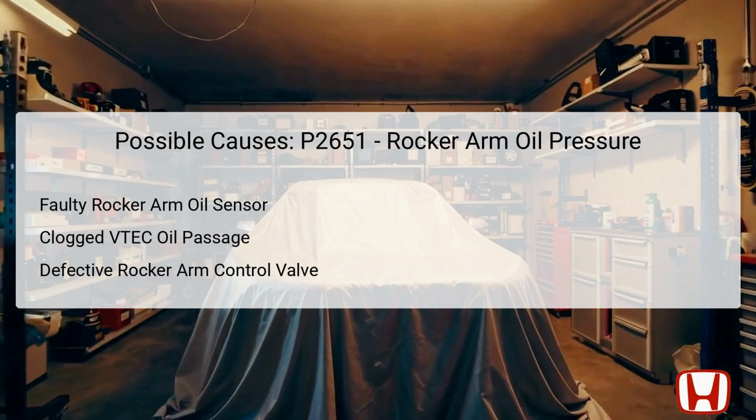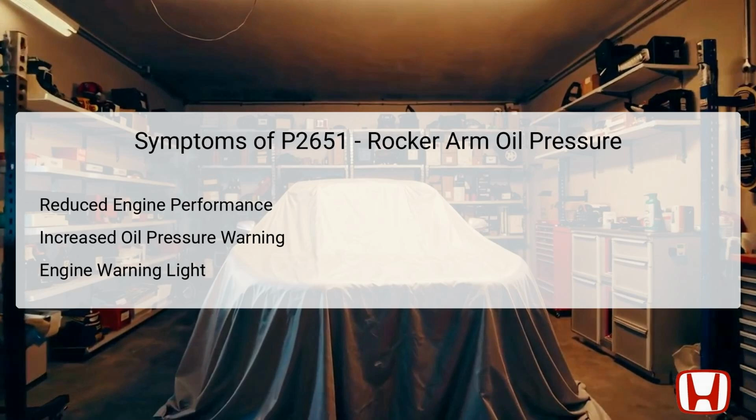Lastly, a defective rocker arm oil control valve can fail to manage oil flow adequately, leading to insufficient pressure and activating the warning code. Proper inspection of these components is essential to ascertain the root cause of the problem and actionable solutions. When dealing with DTC P2651, several symptoms typically manifest that can impact the overall driving experience. One common symptom is a noticeable reduction in engine performance, which may include sluggish acceleration and poor engine responsiveness.